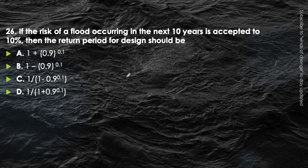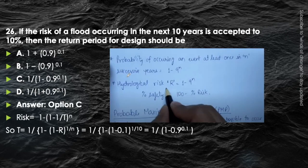In this question, you should first of all know the formula of the risk in terms of return period. The formula for risk is 1 minus q raised to power n, and q is 1 minus 1 upon T. So it can be given by 1 minus (1 minus 1 upon T) raised to power n. That is the risk.